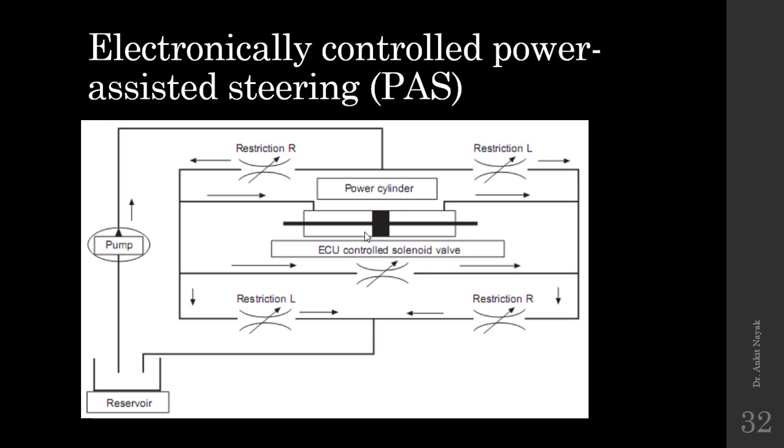Sensors are directly connected with the steering wheel. According to those sensors, the power cylinder is actuated, with different valves associated with the power cylinder, so that the pressure will change inside this power cylinder. This power cylinder will supply the fluid pressure to the different cylinders, so that they can be actuated to give the direction to the front wheels or any associated wheel.